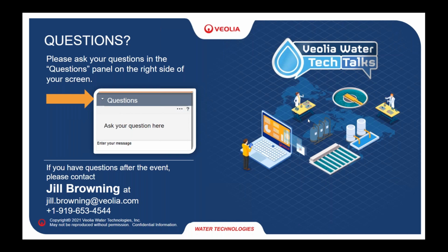Yeah, that's a good question, and one that we certainly have to pay attention to. We are generally more fond of wet chemistry analyzers, and the reason being, in a well-operated, fine-tuned system, the ammonia and nitrate concentrations where you are measuring them in the reactor are typically going to be very low. And you need to have good precision at those low levels. An ISE probe just isn't going to do it.